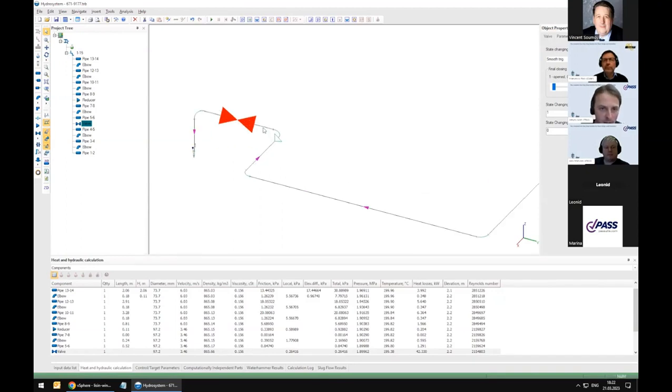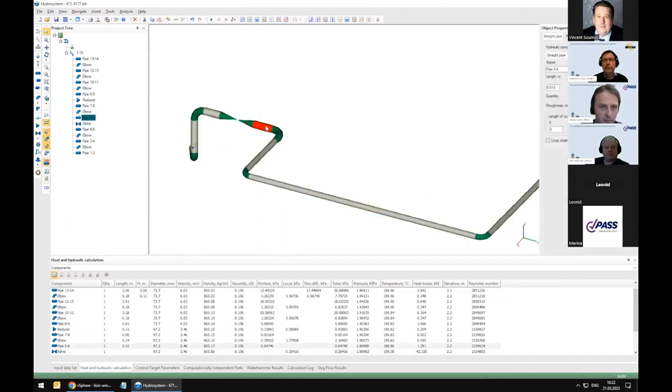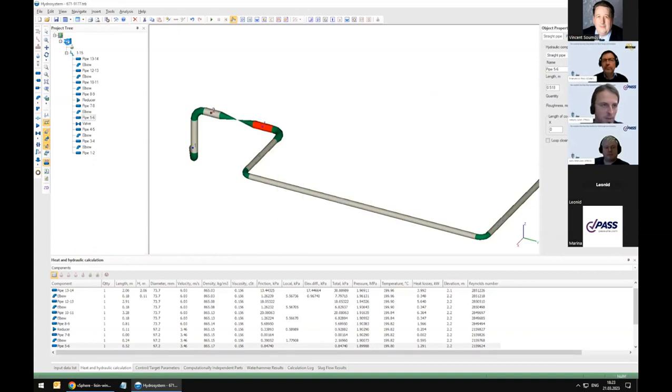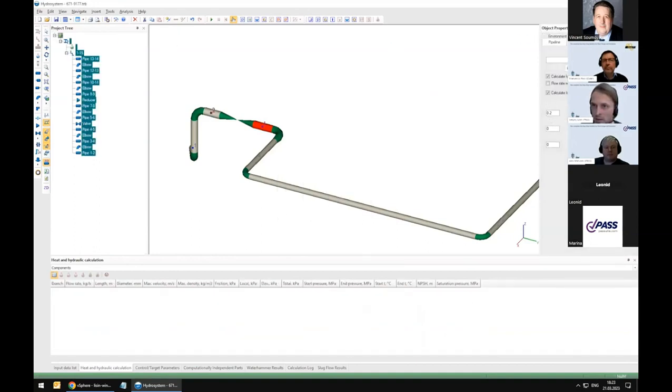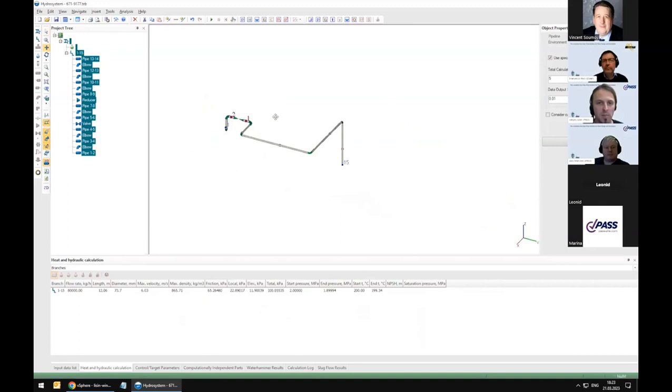And we want to find out what will happen before this valve over here, for example. I'm adding a viewpoint in here, number 1. And what will happen after this valve? Somewhere over here. Okay, and let's set up the calculation settings. For example, let's calculate what will happen within 5 seconds after our valve starts closing. That's it. We're ready to go, ready to perform water hammer analysis.